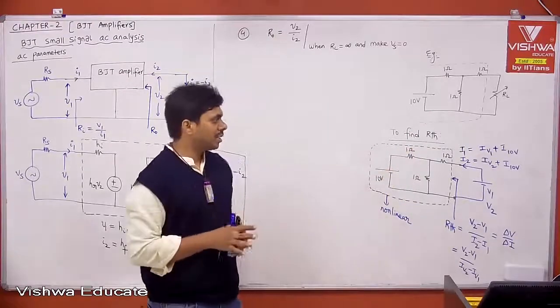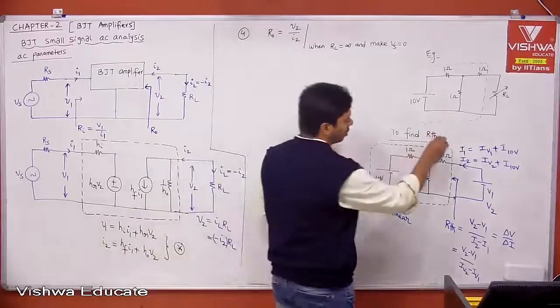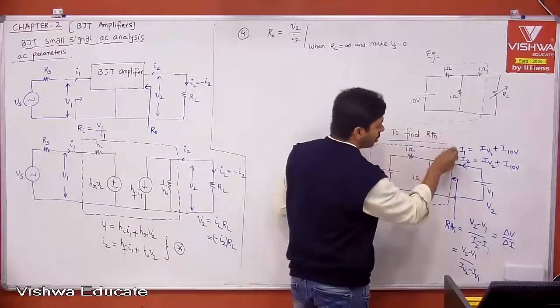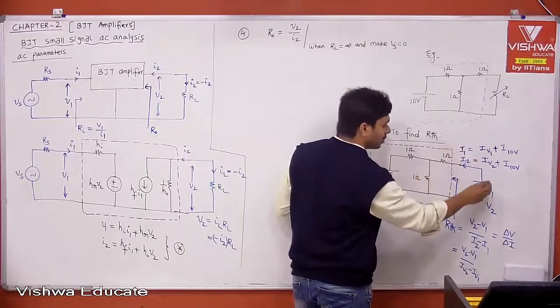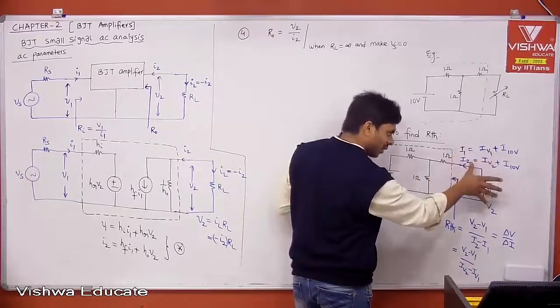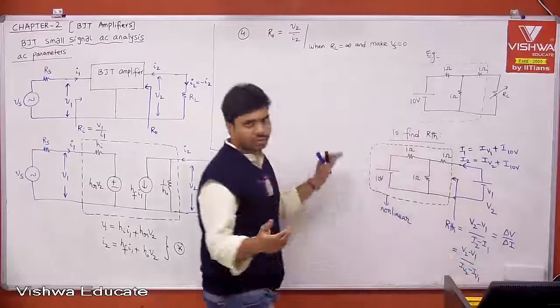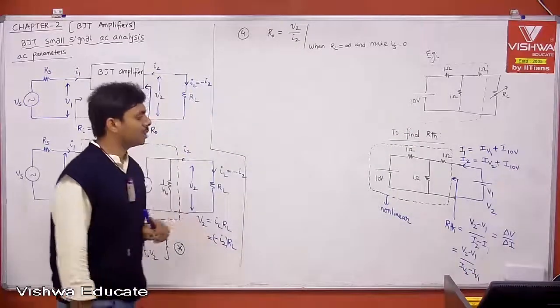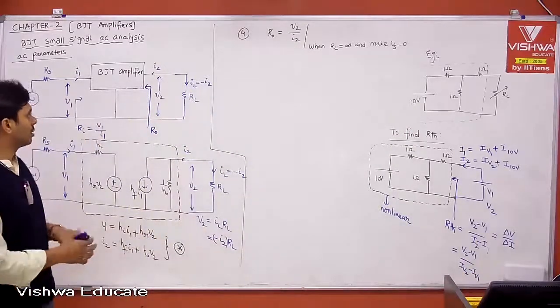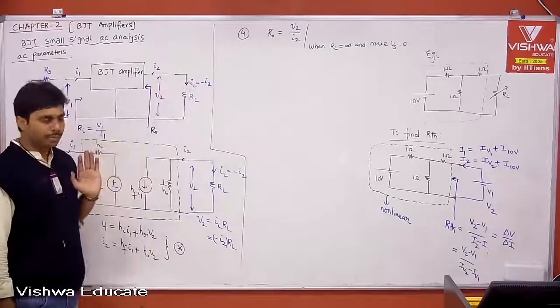Therefore, in a generic way I can say, irrespective of anything, I want to know the change in output current only because of the change in output voltage. If that is satisfied, the problem is over. That is your resistance. Coming back to output impedance. What is output impedance? Exclude the load.